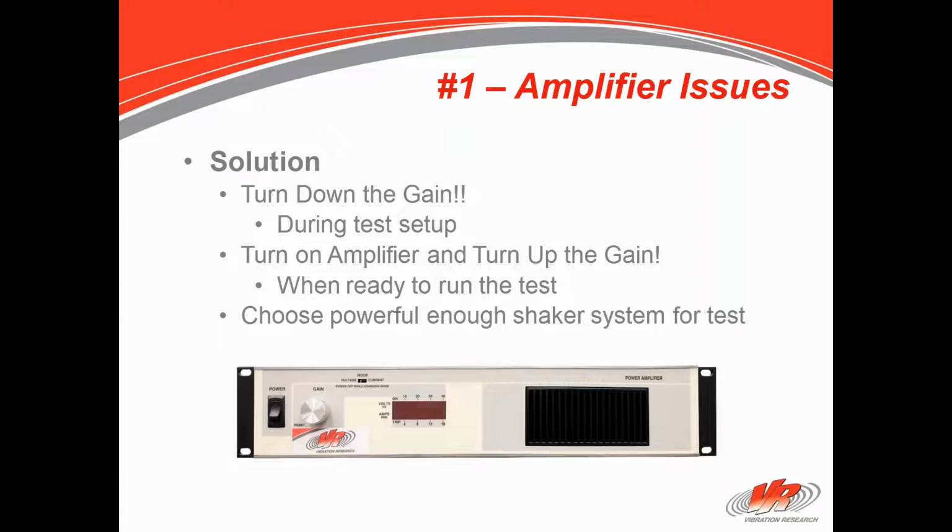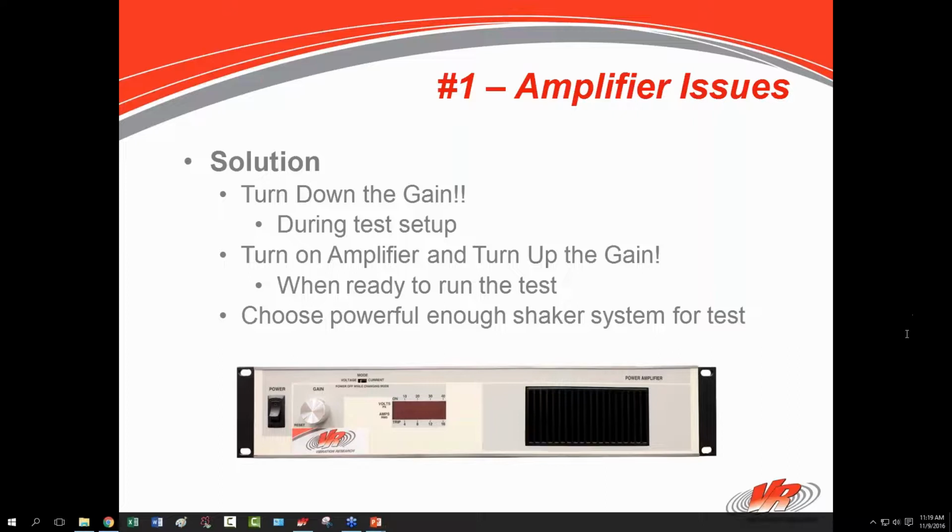Let me digress and go to that question right now. You'll see it come up later, but this is the appropriate time to talk about it. One of the comments made last time was, we always turn the gain to 100%. Am I using up my amplifier or wearing out my shaker unnecessarily? The answer is no. That doesn't actually happen. The gain on your amplifier works with the gain stages in the controller to produce power going out to your shaker. And in the end, that power has to be controlled somehow.